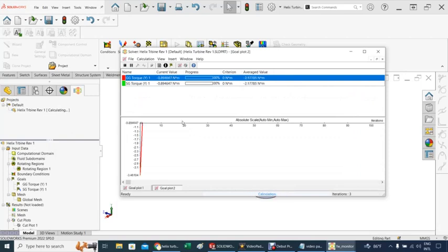So dropping, dropping, dropping, 0.06, 0.04, 0.04, 0.02, bingo, on the positive side. Definitely on the positive side, 0.1, 0.12, 0.13, and it's increasing. So you see, at 1,000 RPM, you have to put power into it. You have to add energy to the spinner so that the spinner can rotate at 1,000 RPM.